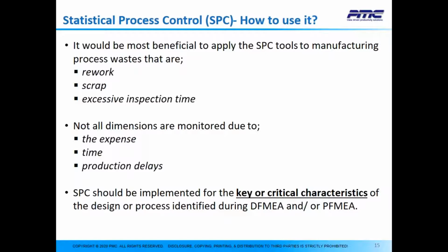So SPC should be implemented for the key or critical characteristics of the design or process identified during DFMEA and/or PFMEA. DFMEA stands for Design Failure Mode and Effects Analysis. PFMEA stands for Process Failure Mode and Effects Analysis. These are the two risk assessment tools we use with product and the process, respectively. Data would then be collected and monitored on those key or critical characteristics.